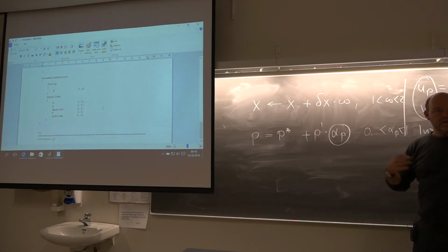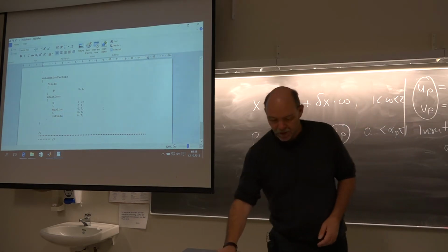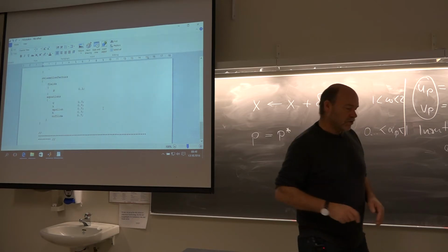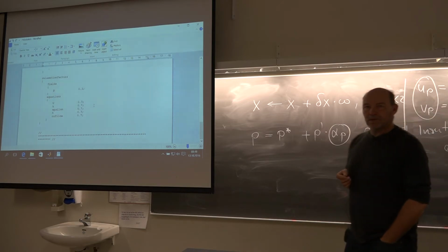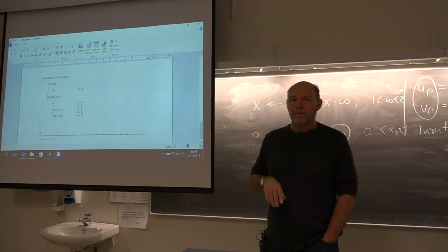Remember, it's a nonlinear equation system here, so yes, we have to do many iterations, and we have to do it carefully, slowly. You can't take too many adjustments at a time. Here you may actually have to use smaller numbers if you have a very complex problem that explodes all the time, no matter what you do. Then maybe you have to go down to 10% or something.